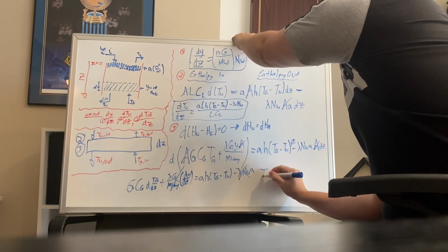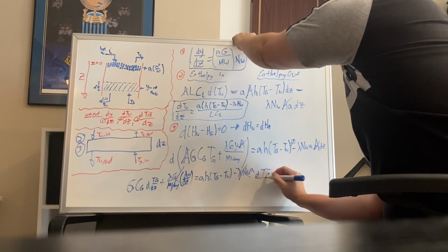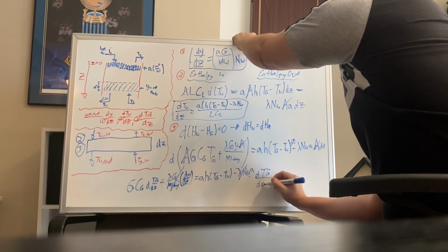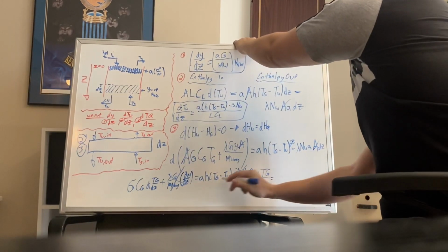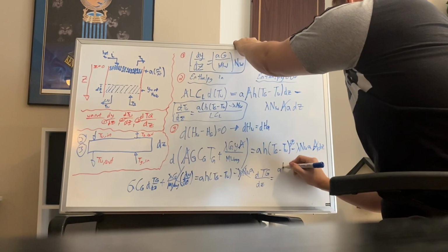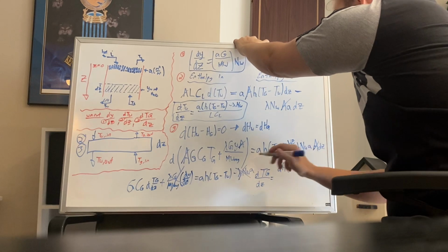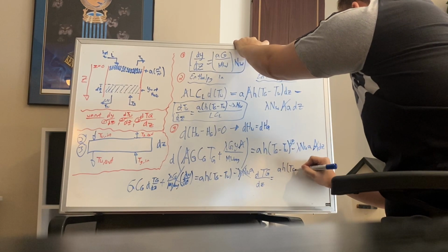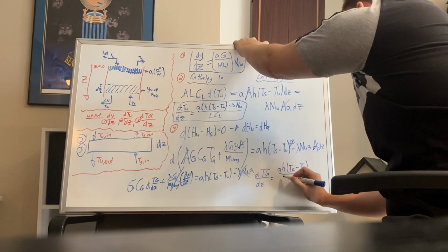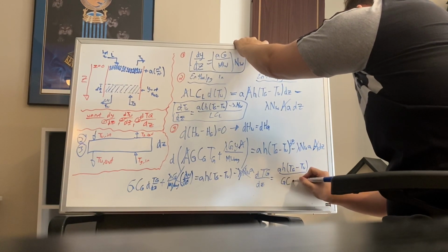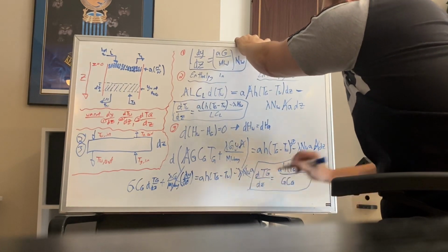So this is actually going to give us our final one here, which is the rate of change of the temperature of the gas with respect to where the air is in the cooling tower, multiplied by this value that's left on this side, the specific area multiplied by the heat transfer coefficient, multiplied by the difference in the temperature of the gas phase and the water phase, all divided by the gas flow rate and the specific heat capacity of the gas. That will give us our third differential equation.